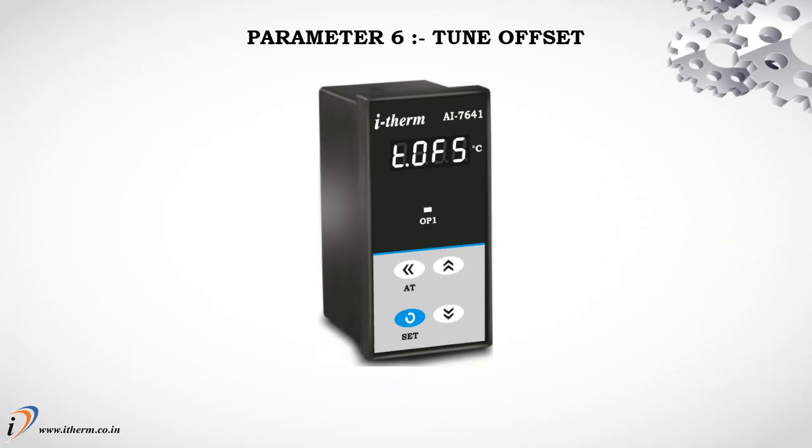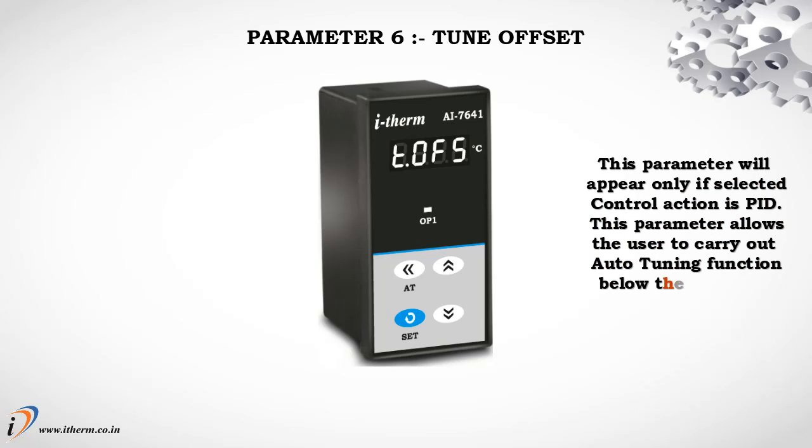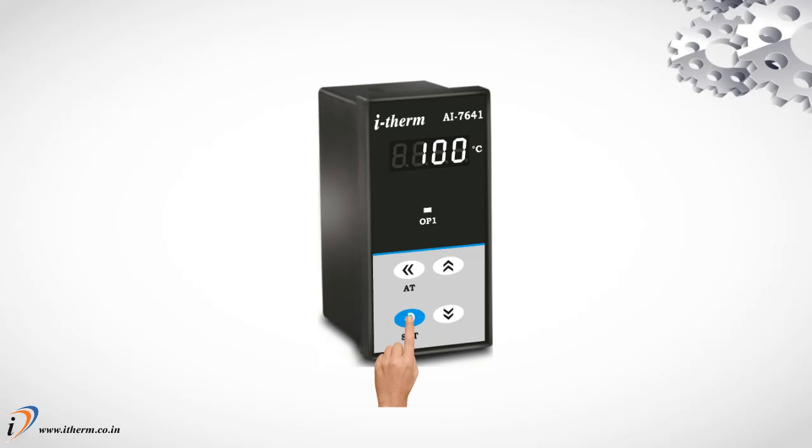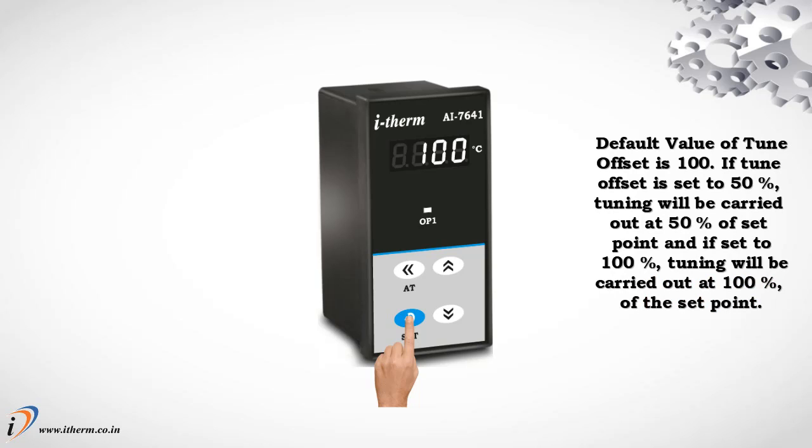Parameter 6, tune offset. This parameter will appear only if the selected control action is PID. This parameter allows the user to carry out the auto-tuning function below the set point. Default value of tune offset is 100. If tune offset is set to 50%, tuning will be carried out at 50% of the set point, and if set to 100%, tuning will be carried out at 100% of the set point.